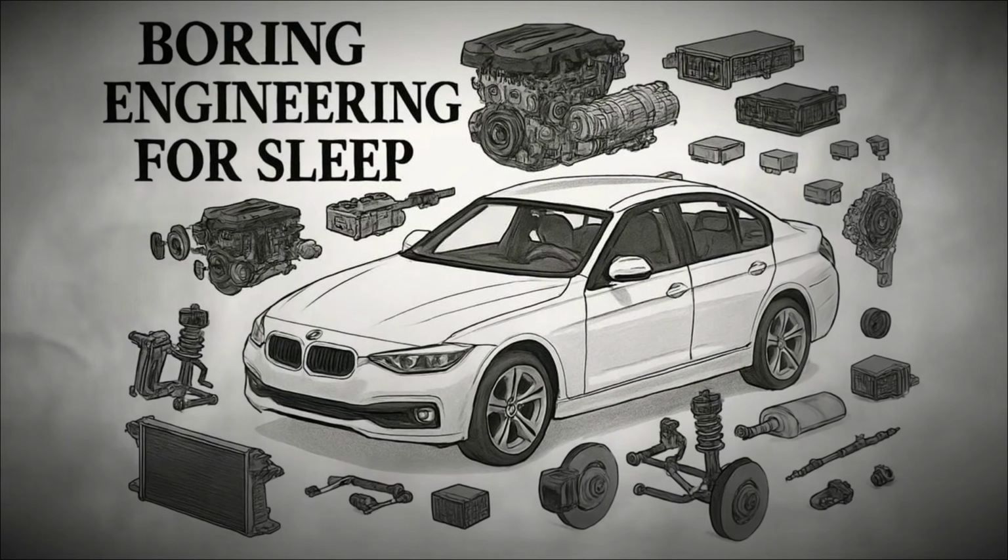The most common is the wet sump system, where oil is stored directly in the pan under the engine. A less common but advanced design is the dry sump system, used in racing and high-performance cars, where oil is stored in a separate tank and pumped into the engine. This prevents oil starvation during high-speed cornering and allows the engine to sit lower in the chassis.